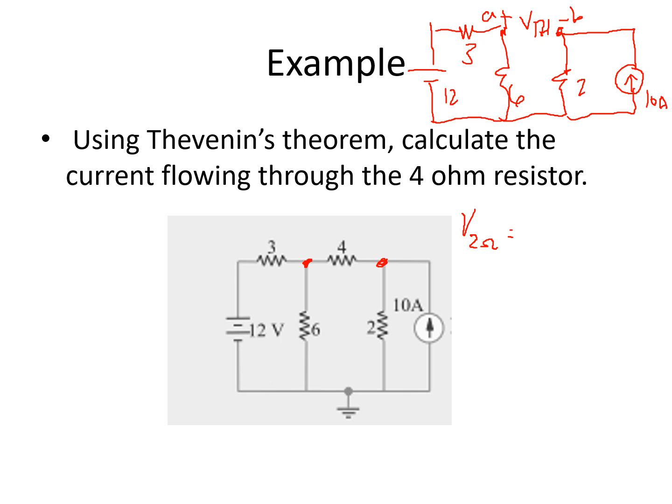So the voltage across 2 ohms is equivalent to 2 ohms times 10 amperes. We have here 20 volts. That is the voltage across the 2 ohm. And what is the polarity? So since the current will be flowing in this manner, okay, so this is plus and this is minus. So we have here plus and minus 20 volts.